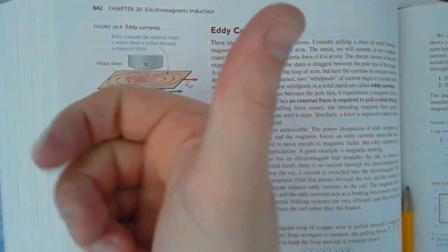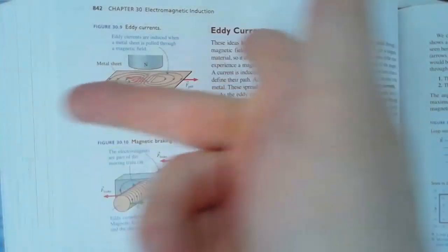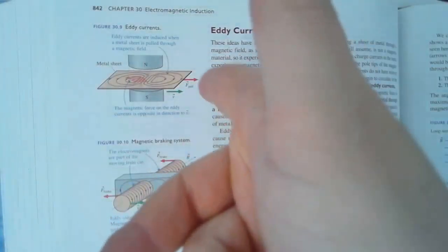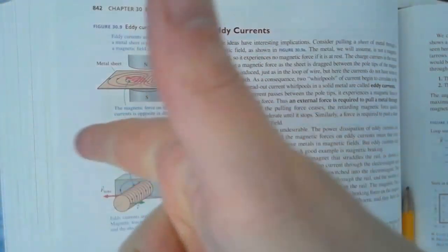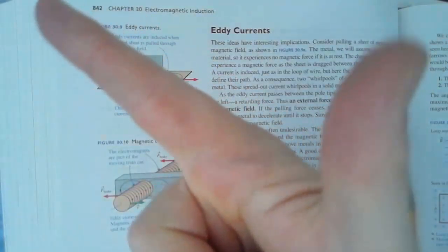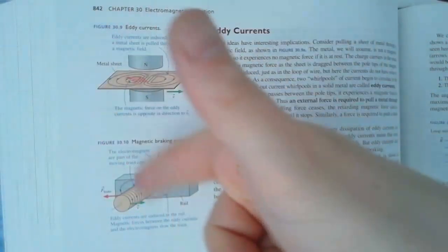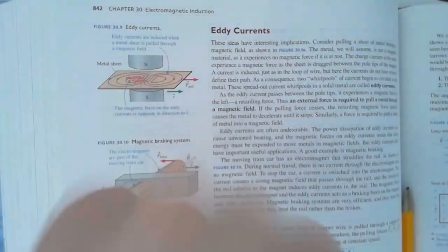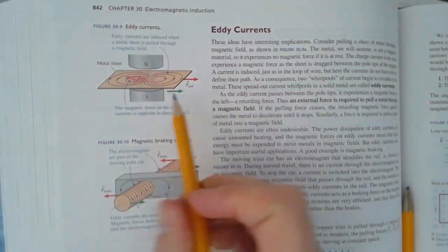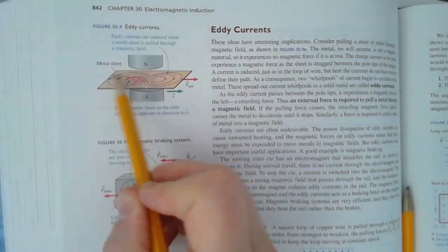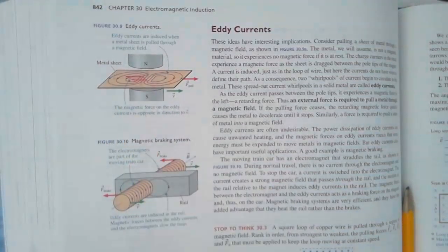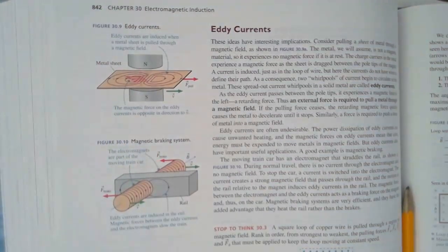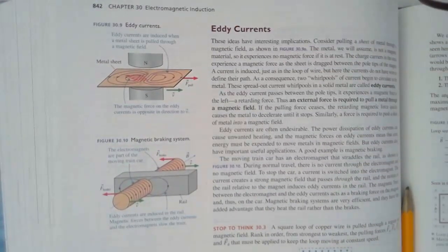Now, you use your rules, and you're going to get a force to the left, right? So, current into the page, hard to show you. Field from north to south, you can do this. I'm going to break my wrist here. The force, you can double check, is a braking force backwards. So I get an eddy current, at the same time I get magnetic braking. And that's close to the kind of principle you might use, say, if you want to brake a train.